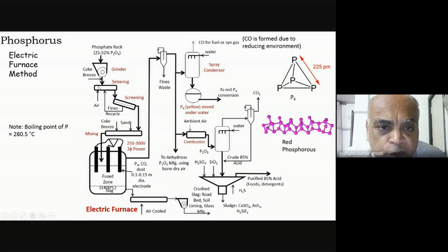And I'm introducing air to heat it. And at the high temperatures, it will sinter. So when it sinters, I will get big particulate matter. Heavy stuff. But all of it may not have sintered. So some amount of fines may still remain, which will be very fluffy. And that you cannot introduce into your electric arc furnace. So the best thing is that you screen it. Screen it means obviously pass it through a sieve where the fines will get removed, and those will basically be put back over here.